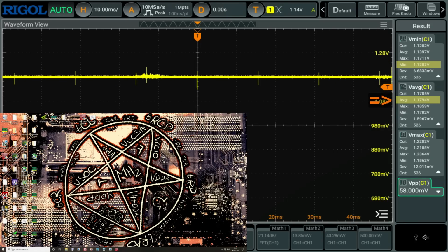So in a perfect world, average voltage and minimum voltage would be the exact same thing. Unfortunately, due to physics and imperfect real-world components, actually mostly due to the imperfect real-world components, your minimum voltage will never be the same as your average voltage. But if you have the load line calibration set correctly, you can get pretty close, especially if the motherboard is also well designed. So that's what we're aiming for.